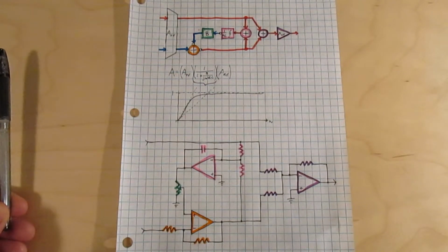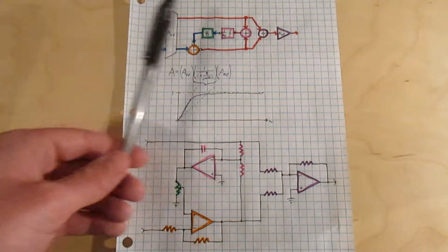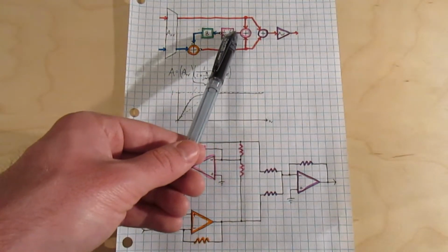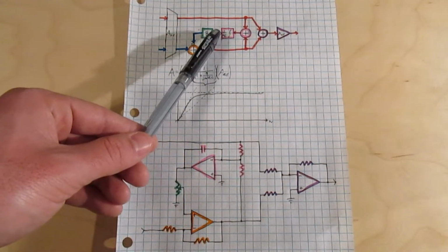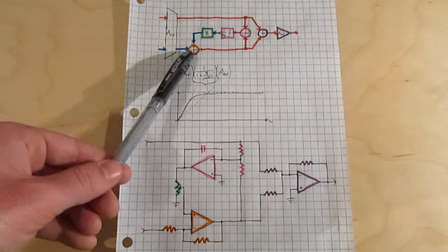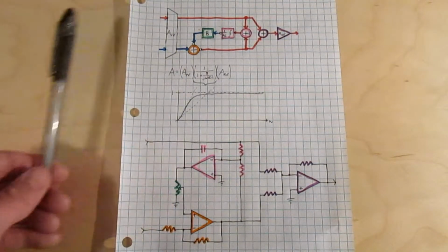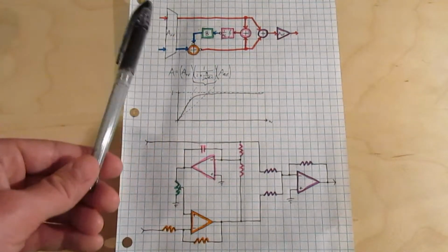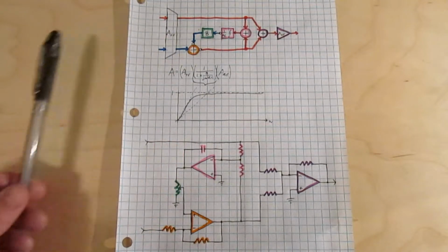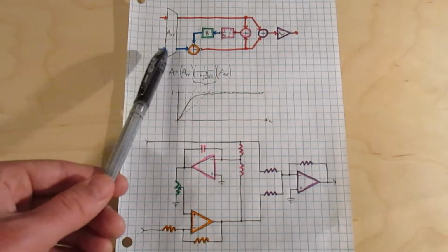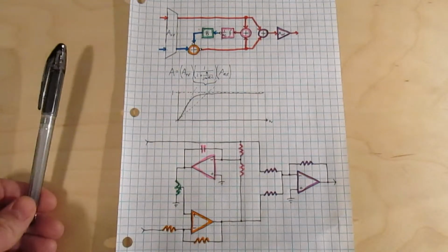A good way to think about this is that the integrator will accumulate its input over time. So if there's a DC offset at the input to the integrator, then the output of the integrator will keep climbing and climbing and getting larger. Now normally that would just get subtracted from the input until it cancels out all the DC offset, but with the attenuator, it only subtracts off, let's say, half of the output of the integrator. Because the output of the integrator is going to keep on climbing, it'll eventually get to the same point, but it'll take about twice as long to get there.